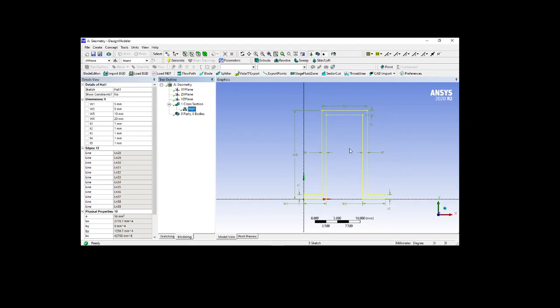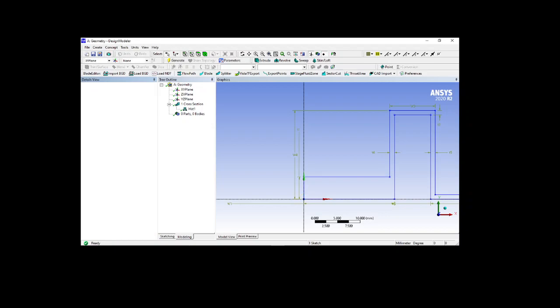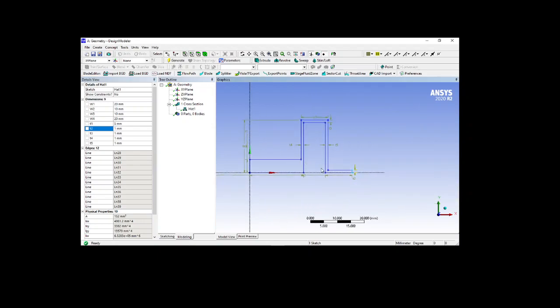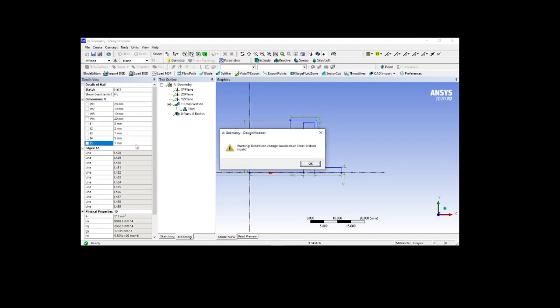There are a lot of dimensions they have prepared, and if you want to make some changes you can do it here. I will use 20, and here I will use 10, and here I will use 5, and this will be T2. As you are watching here, the T2 gets highlighted when you press this one. Okay, when you press the geometry it will get highlighted. This is the T4, of size 5. Next W3 and T3. Just give some dimensions of the type you want, then generate.